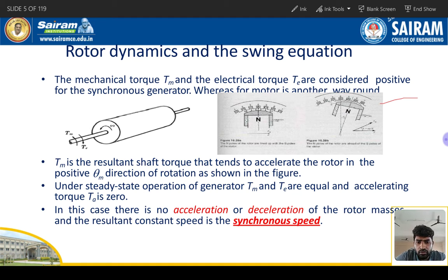Keep it in your mind. The rotor has a field winding and the stator has the stator armature conductor, which is stationary, right. So, when the rotor starts rotating, there is an electrical output as well as a mechanical output. I already told you torque is nothing but a twisting force, right. So, at the time of starting, if a power failure occurs suddenly, the rotor sometimes will swing, right. So, Tm and T will be there. Tm is the mechanical torque or mechanical output of the motor, and T is the electrical torque.